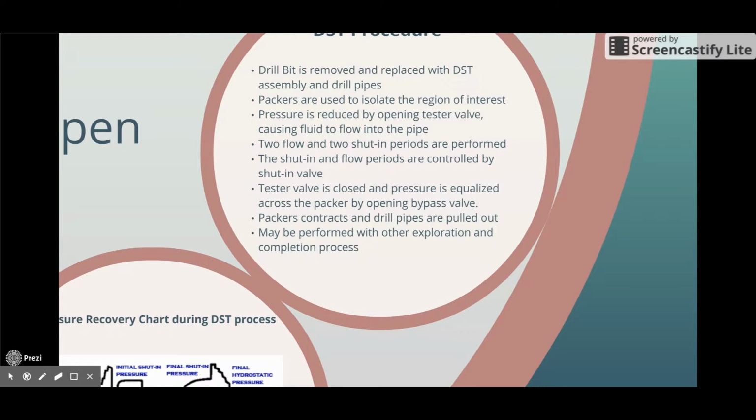It is compressed and expanded by supplying the weight of the drill string on the packer. These packers isolate the lower zone from the rest of the wellbore and isolate the region of interest when we are conducting the test. The tester valve is open automatically a few minutes after the packer is set and the formation fluids enter the pipe. The tester valve stays open until the test is completed and the packer is unset.